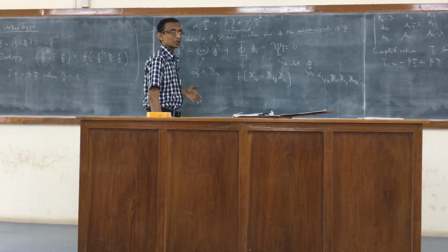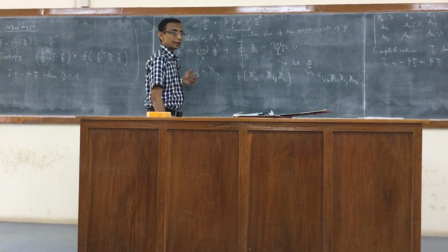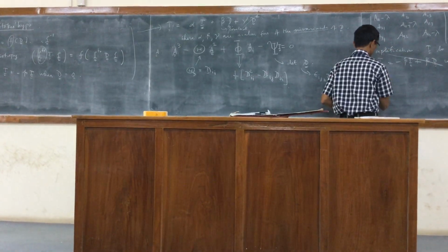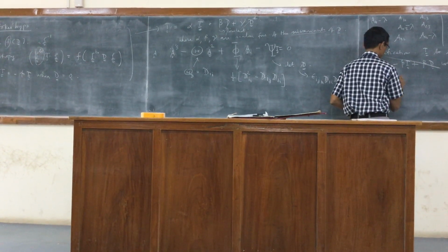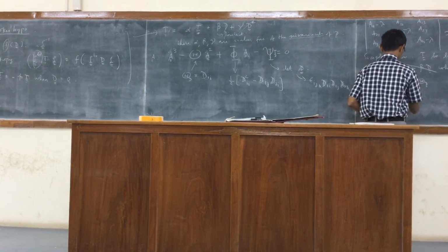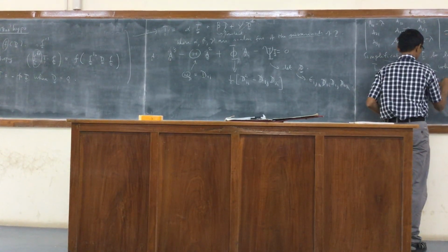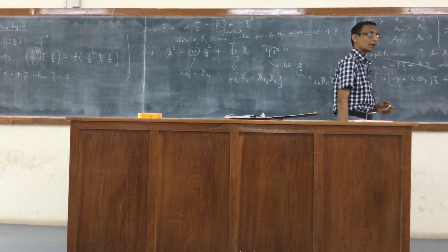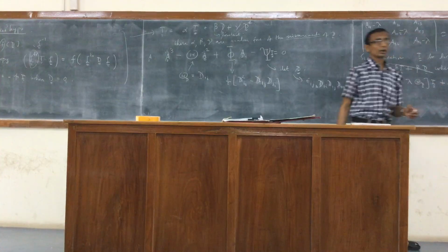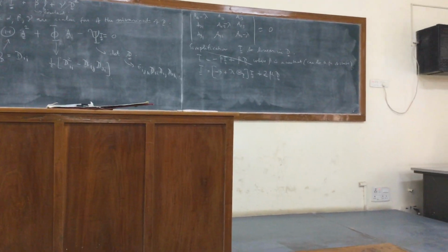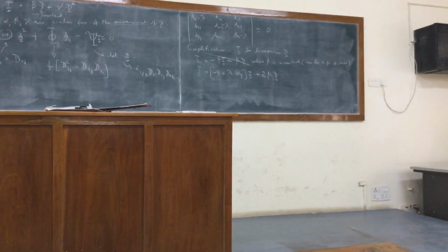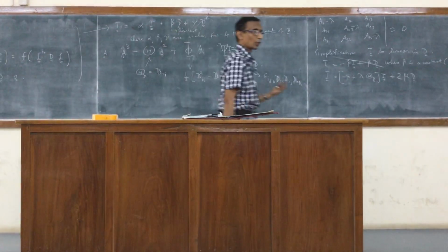So alpha can be a function of the trace of D. The most general form is not quite this, but I can write this as minus B plus lambda times I plus, and I will simply call the beta to be twice a quantity mu, which is what we know as the dynamic viscosity. I'm just replacing beta by 2 times mu. That is what it would turn out to be.